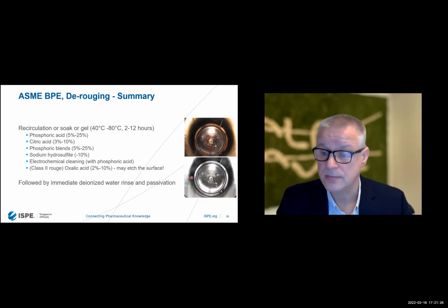Thank you. And on WFI, Shirley Chow asks, the WFI system is operating 24/7. Rouge unavoidably forms. If we have to de-rouge and passivate every time we find rouge, basically we need to do that every year if we perform a visual inspection. This is very costly and time consuming. A shutdown is usually required to do this. So it asks, is there no recommendation for a more quantitative acceptance criteria?